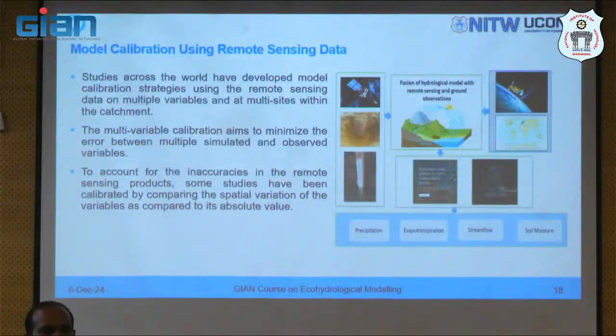Now in both the cases, your water extraction from different soil layers is different, but you are getting a similar accuracy. Now your combination of parameters may lead to a same solution, right? And that is what is your equifinality problem. So it goes back to what Professor Chaubey was telling. You are getting the right results for the wrong reasons, right? The stream flow accuracy is good, but your simulation is wrong, okay?